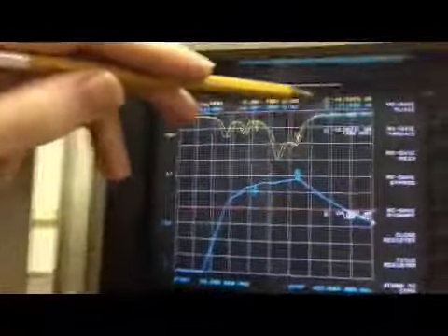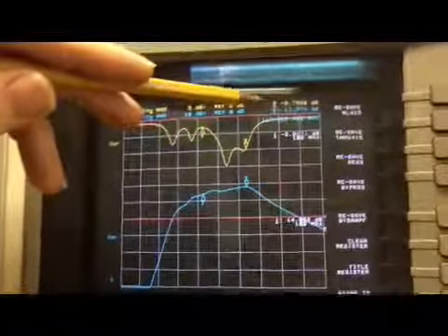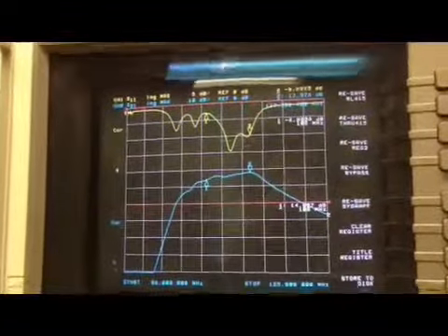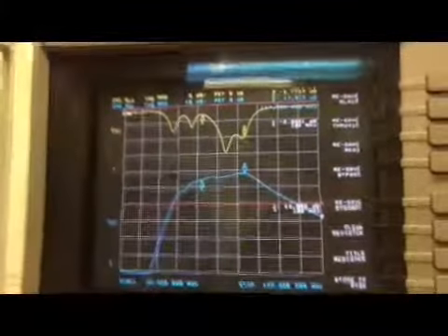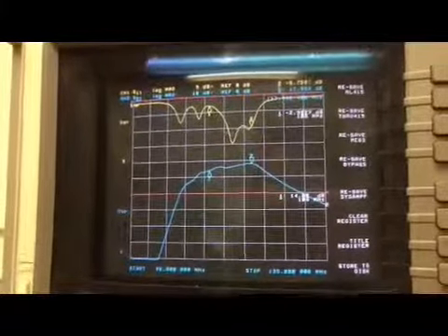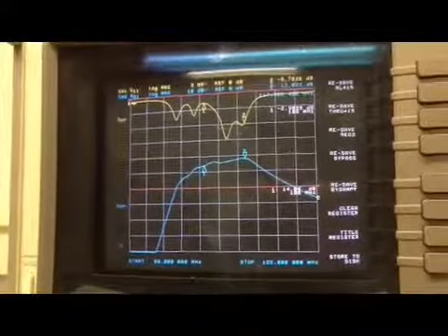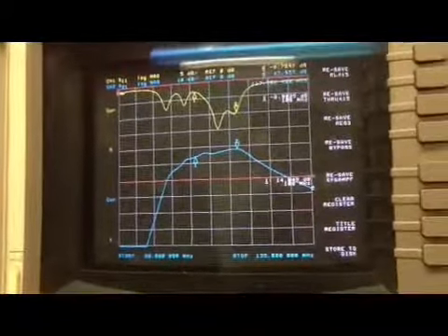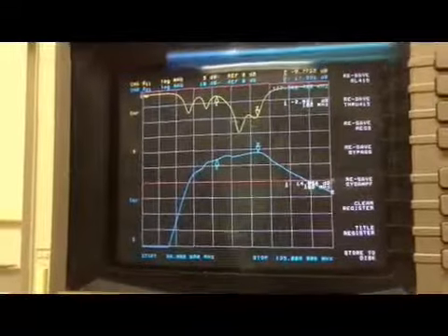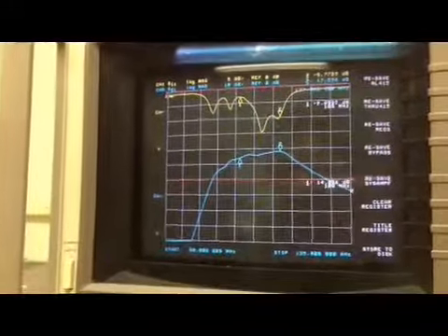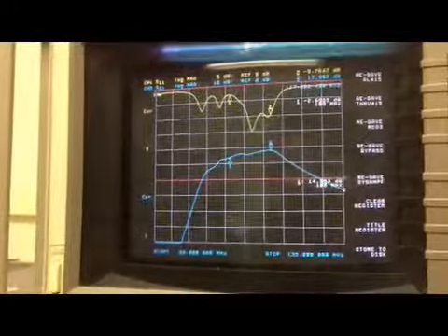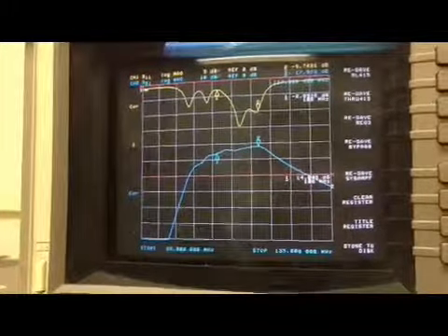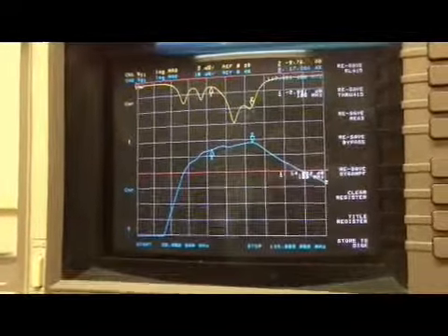And channel 2, we're still showing nearly 18 dB, so using this closer spectrum we can see that we're just 2 dB shy of having 0 dB attenuation, which is amazing considering that we are using a tuned splitter. Generally, the best that you can see with just a quick and dirty splitter is 3 dB of loss, more likely 6 dB, but this is what we have and this is working, which is great news.